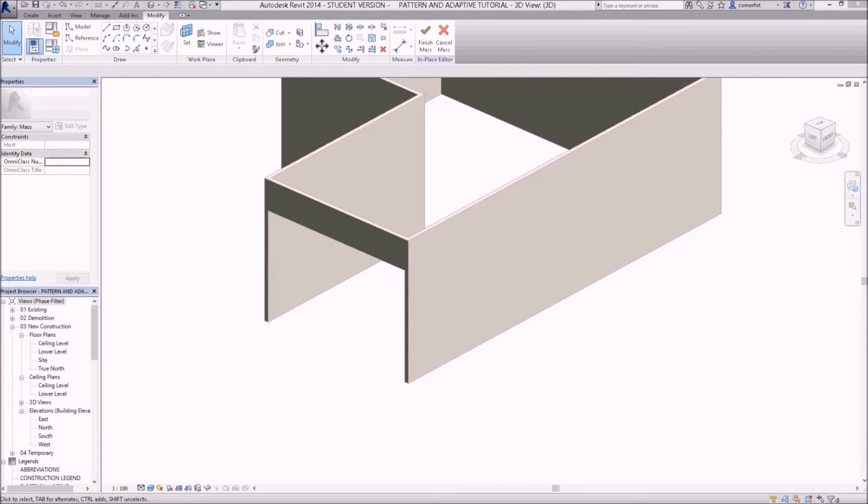So what you can do here now is, if you find your curtain panels down underneath here, which we've created, there's a curtain panel, truss braced, open that up, and what you could do is right click on that and duplicate. So you might want to create another one called frame 50 with a brace of 20.